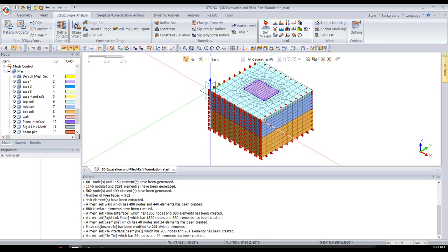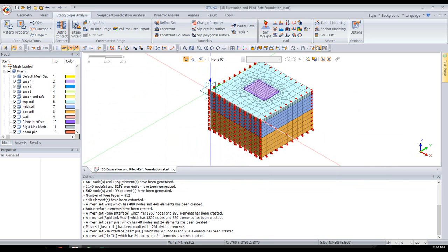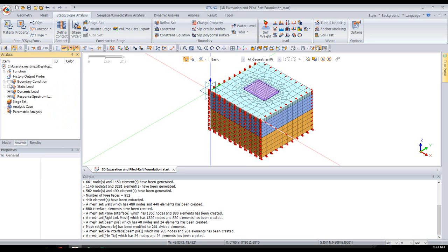First, of course, would be self-weight, basically gravity. All you got to do is tell it the direction of gravity is in the vertical Z, and we'll have a big arrow there. I'm now going to move in the workspace to the analysis tab and deactivate these.